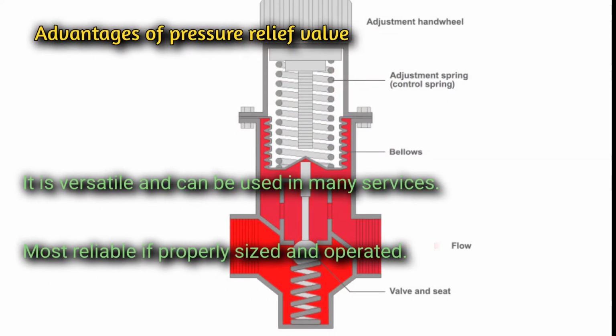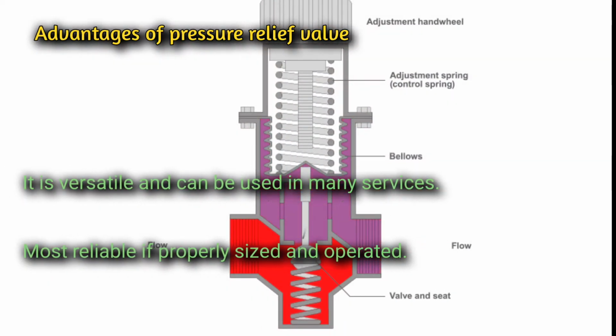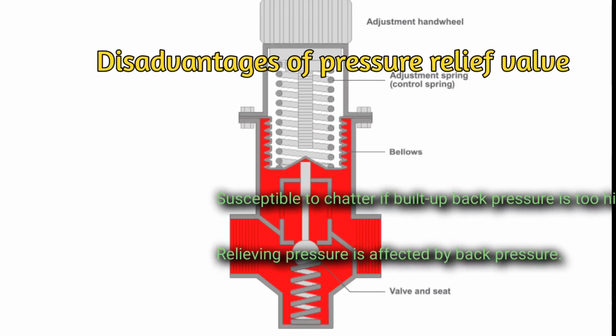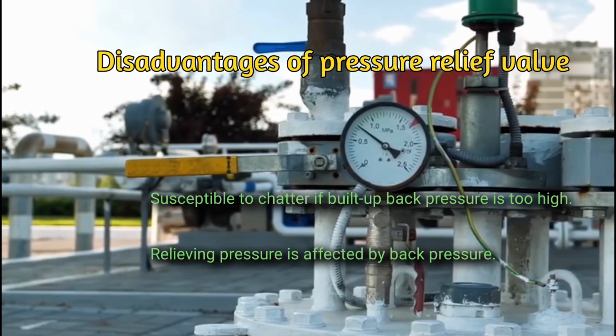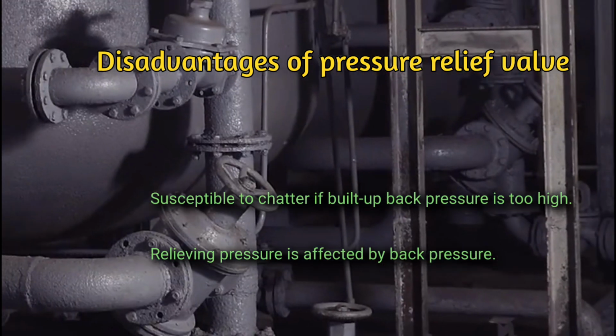Advantages of pressure relief valve. It is versatile and can be used in many services. Most reliable if properly sized and operated. Disadvantages of pressure relief valve. Susceptible to chatter if built-up back pressure is too high. Relieving pressure is affected by back pressure.